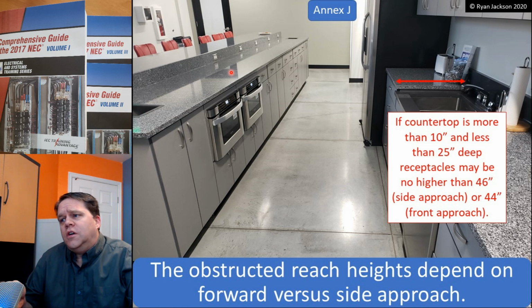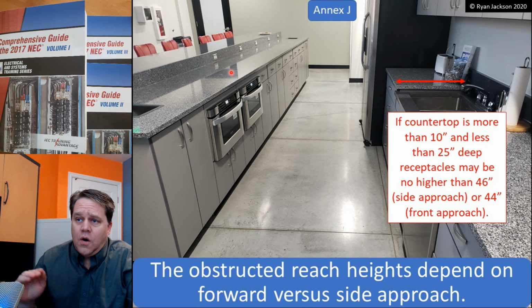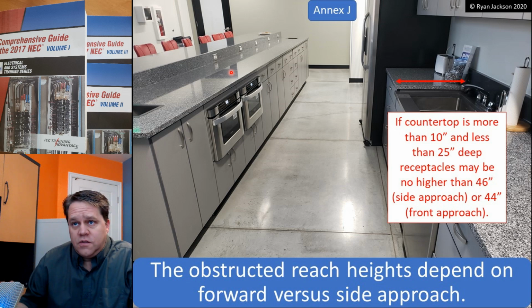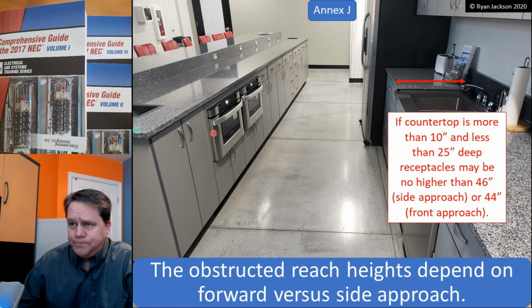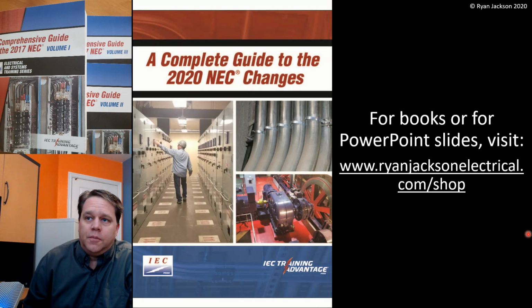So usually that part of the issue is self-satisfying, but we would need to figure out how deep that obstruction is, and that would gauge how high my receptacle, light switch, garbage disposal switch, things like that, how high those could be. Things like a built-in microwave, pretty much out of the picture, right? That would not be allowed at all. If you had a microwave in this room, it would have to be on the counter. You can see how these ovens are down low. Perfect. Those meet for accessibility. So we have to make sure that we can reach these things. 15 to 48, highest and lowest reach range for operable parts.